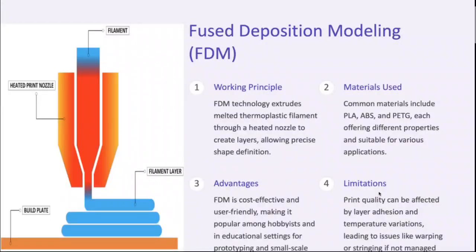Another limitation was that, as the parts are printed using thermoplastic, they deform or easily react to temperature. If we use the part at 60 to 70 degrees centigrade, it will slowly deform its shape as it is made out of thermoplastic. Apart from that, FDM is very good, and we can make whatever we want. It is a very flexible and very useful 3D printing technology.